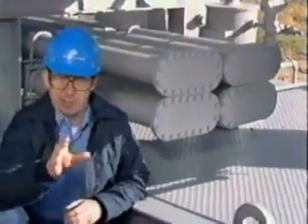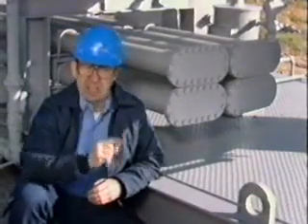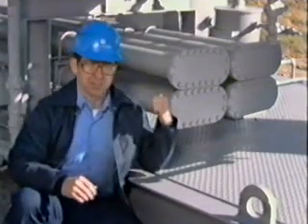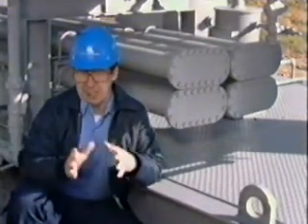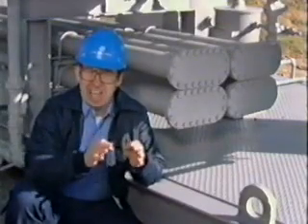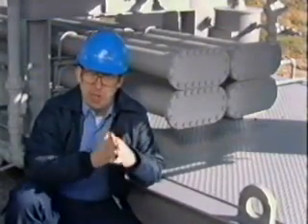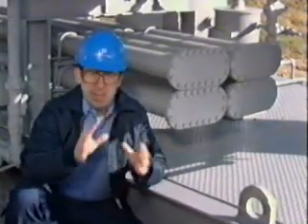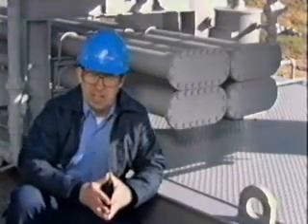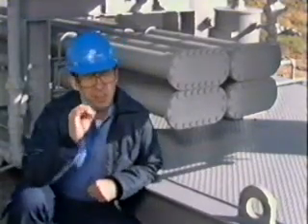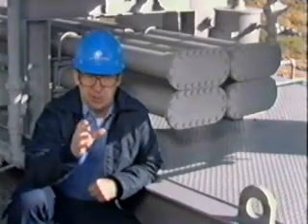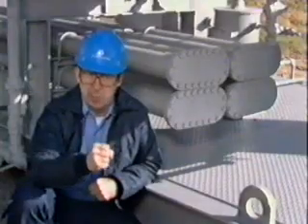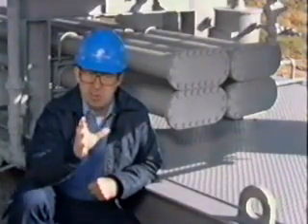There are two types of heat exchangers used to cool the glycol in a glycol dehydration unit: glycol to glycol heat exchangers, like these, and a glycol to gas heat exchanger. Now, lean glycol leaving the surge tank must be cooled prior to entering the contactor. The cooling allows the lean glycol to absorb the maximum quantity of water from the gas in the contactor. The heat exchangers are very important in the overall operating efficiency of the dehydration unit. They substantially reduce the amount of heat required by the reboiler and allow maximum gas drying in the contactor.